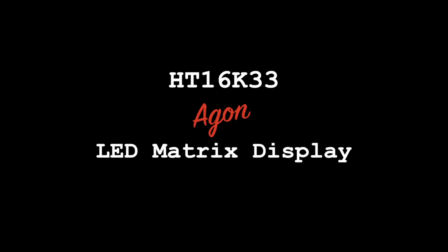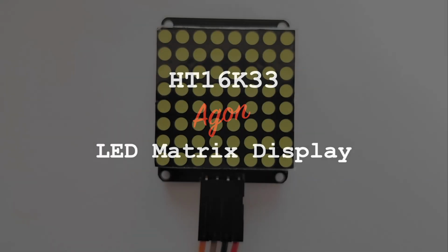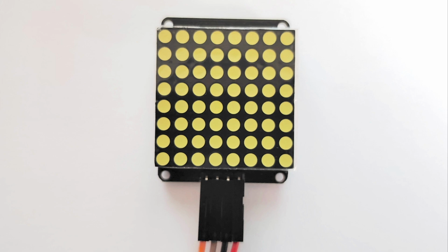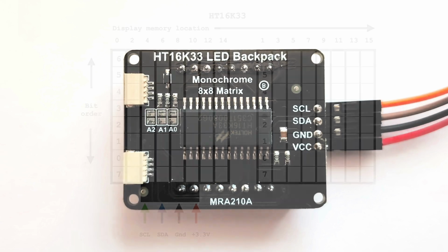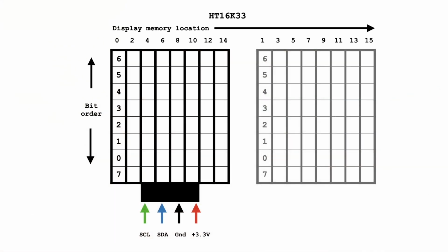This time we're going to be looking at an LED driver chip with an I2C connection. This particular module has an 8x8 LED matrix. On the back you can see there are some solder pads if you want to change the default address on the I2C bus. This particular chip is used for driving various different sorts of LED products, not just this 8x8 matrix, although this is quite a popular one.